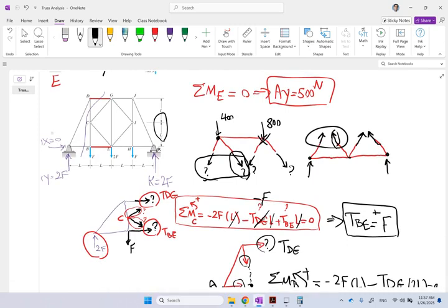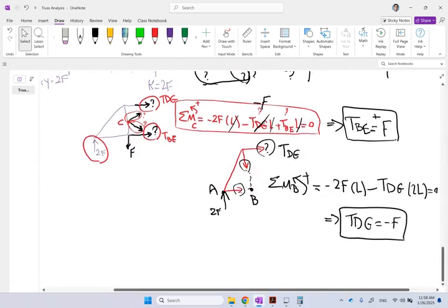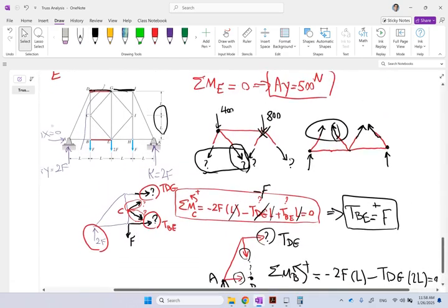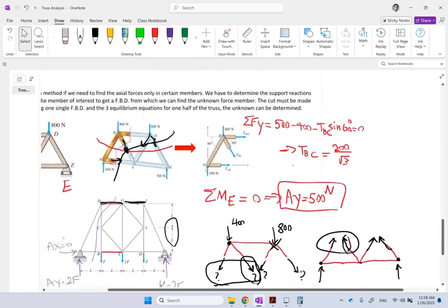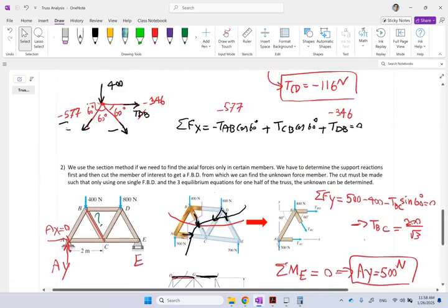And they are not equal, of course, because about the horizontal axis, the mid-axis, this thing is not symmetric. Okay, I can say these two are equal because it's symmetric, but these top one and bottom one are clearly not, and these are the results. So you can use more than one section to get what you need. And this is how you use the section method.